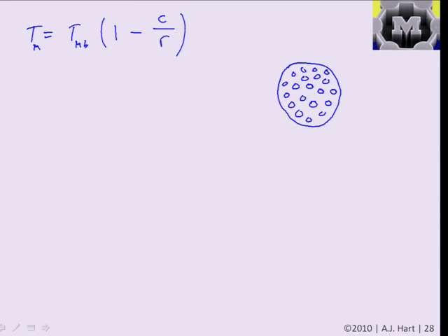And basically the idea here is that if you have a bulk material, then you can say that each atom has a certain cohesive energy, a sort of certain bonding energy. And if you have a smaller material, then you're going to have to, even in the bulk material, you have to subtract some energy due to the surface, like we did at the beginning of the lecture today. But if you have a much smaller material, then the surface becomes more important. So the total energy of this solid per atom is going to decrease more because you have more surface, and you're going to have to subtract more of a contribution due to the surface per atom.